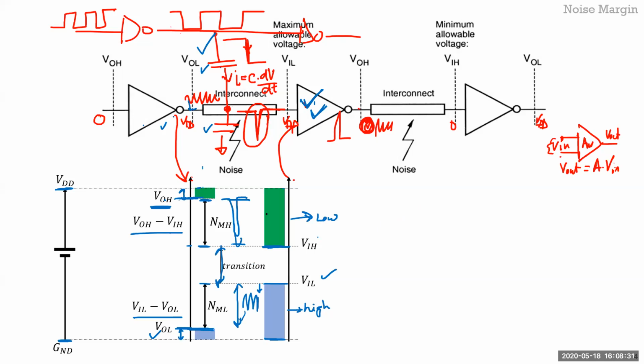This is to guarantee that whatever you are designing, let's say you're designing an ALU, the ALU will still function as an ALU, or you're designing a counter, your counter will still function as a counter. You go below that, all bets are off. You don't know. You can't be here. So this is your forbidden zone, basically, as far as digital is concerned. But in analog, actually, we use this. We create amplifiers, high-speed amplifiers are actually created in this region, just for information. But for digital, there's no such use.